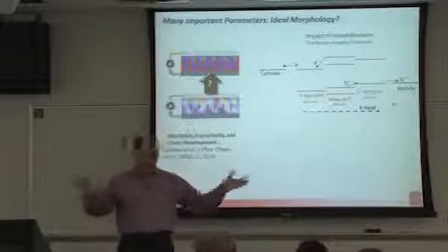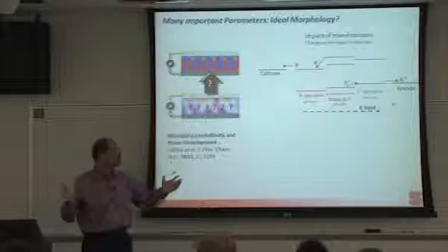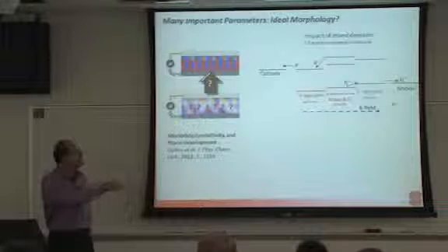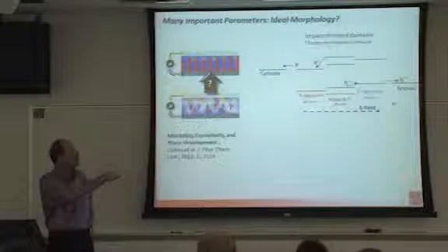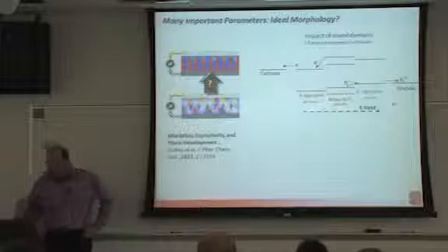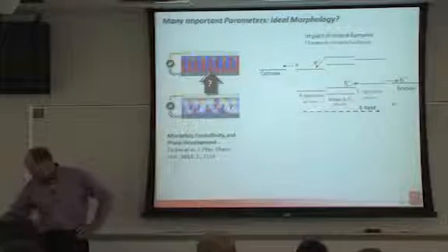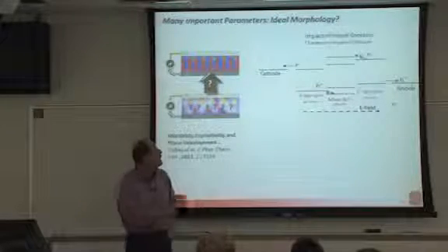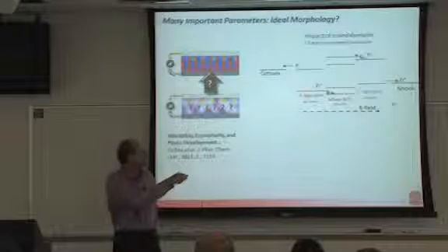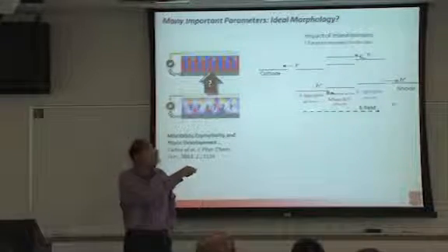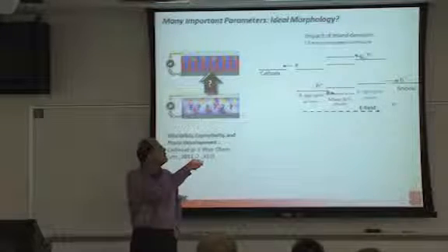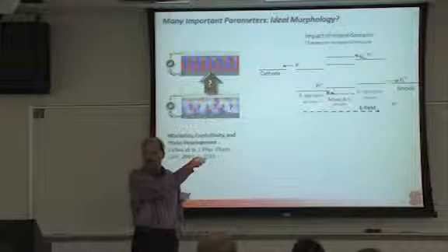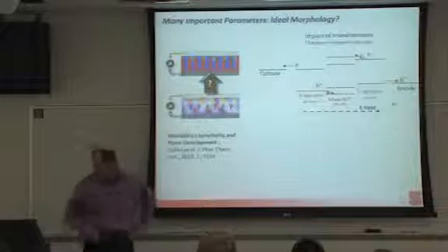I might actually want to optimize the volume of that region, because this is one mechanism to drive the charges possibly out, okay? If I have enough connectivity of the aggregate phase to the electrodes. Now if I absorb in the aggregate phase, it certainly wouldn't want to go as a whole through the polymer. It would have to split at this interface and go as an electron through the mixed phase, and the same is true for the hole.